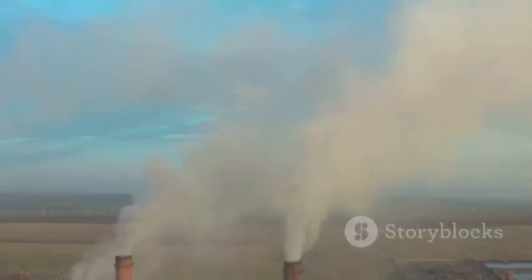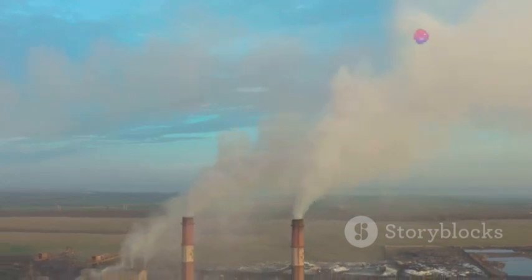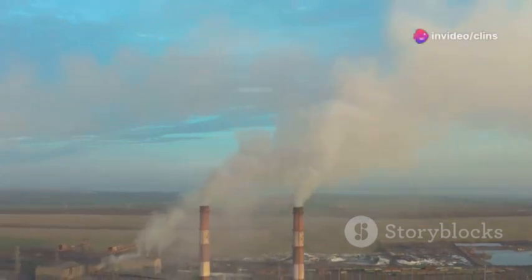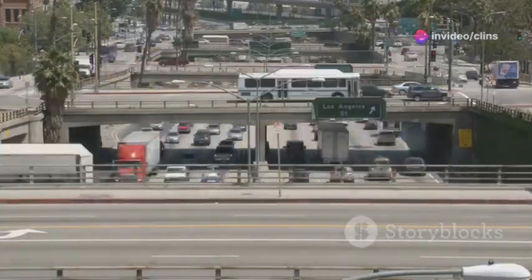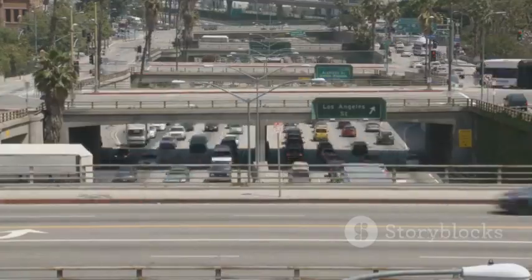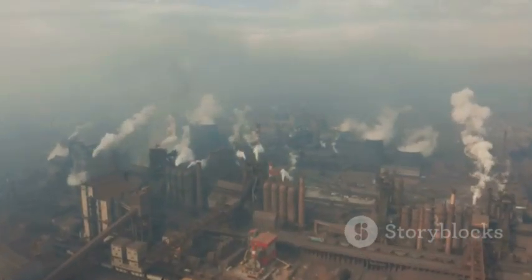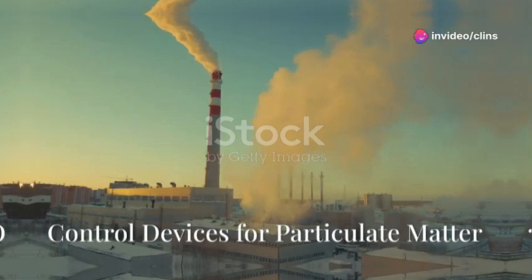Moving on to dispersion models, the Gaussian plume model assumes a steady-state plume from a continuous point source, describing pollutant concentration as a function of downwind distance, crosswind distance, and height. The line source model is used for pollutants emitted along a line, such as road traffic emissions. Lastly, the area source model is used for emissions from large areas like industrial zones or cities.